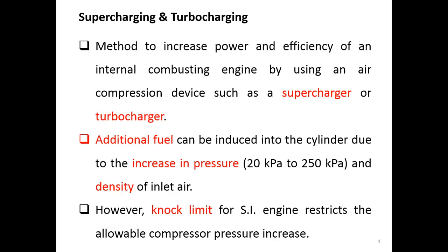But there is a limit on introducing this air, because of the knock limit for the SI engines. In SI engines, if the pressure of the air increases too much during compression, knock may happen.